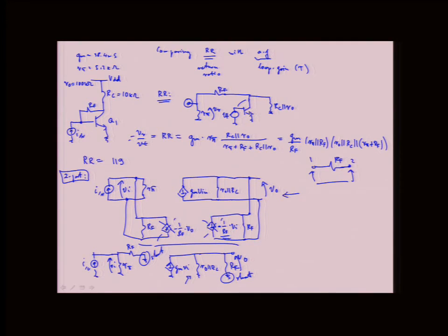And we said that when we did return ratio analysis, it took care of that explicitly through A0. And here I can keep it. If I recognize that it's happening in this 2-port model, I can keep it, and then my 2-port will be accurate. But if I go with this, I explicitly don't acknowledge that there is a flow of information through the feedback section, and I'll make some error.